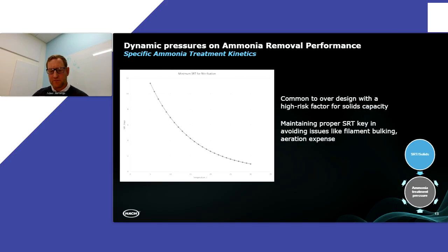The temperature and the solids concentration all come together in this mixture that we need to maintain to keep nitrification rates at the levels that we need in all the seasons. So it's a dynamic process that we have to constantly monitor and maintain, keeping proper solids concentrations that equate to the right amount of bugs to treat nitrogen, ammonia specifically, to the levels that we need to.